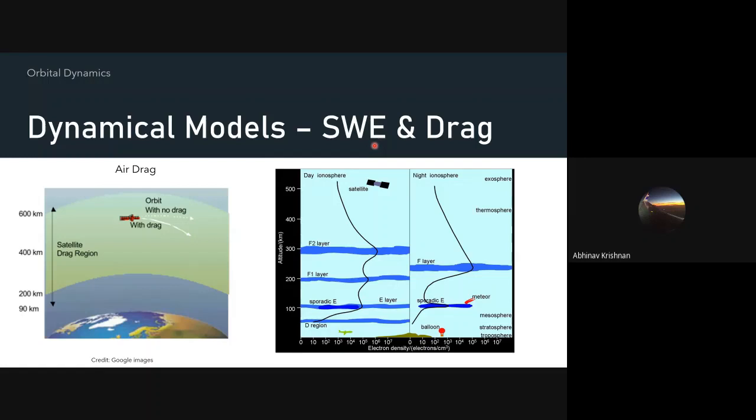Whenever you are in a period of higher solar activity, you will experience the expansion of the atmosphere, the ionosphere, and that significantly affects any satellite flying in that particular part of the atmosphere. It will not be as much as in the troposphere, of course, but the amount of drag you would experience would be significantly higher during a solar cycle, whenever there is a solar event like a coronal mass ejection, or if it's just a higher solar activity part of the 11-year cycle.